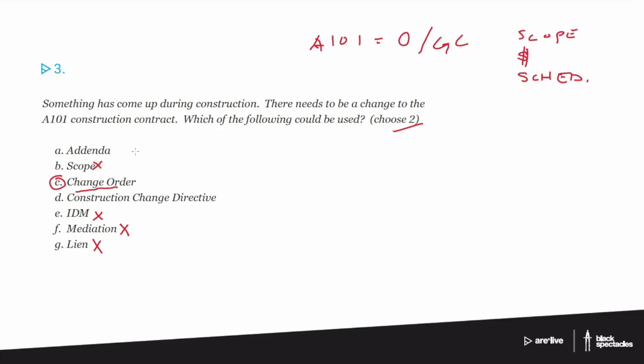When we're putting the bid packages together, you've got drawings, you've got the spec book, you've got the project manual, you've got the forms that the contractors are going to fill out. You're going to give all those pieces of information to the various different bidders. They're then going to ask you a bunch of questions. You can't answer those questions directly because you don't want anybody to have more information than anybody else.